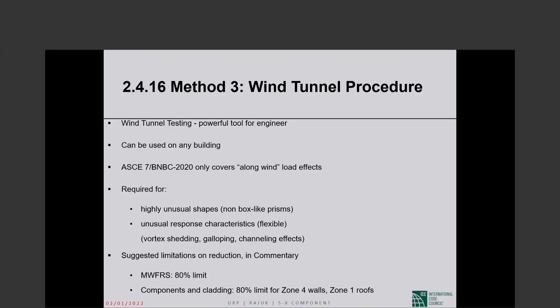There is now a wind tunnel test standard that ASCE publishes, but all of that for you is in the future. So in ASCE 7-05, in the commentary, ASCE's Committee 7 told you when you design based on wind tunnel testing, do not go below 80% of the values that ASCE 7 would give you for your main wind force resisting system.